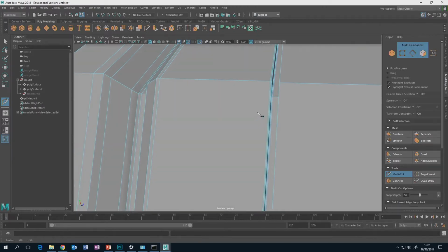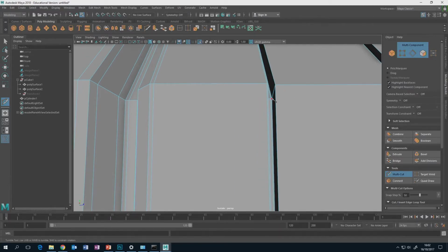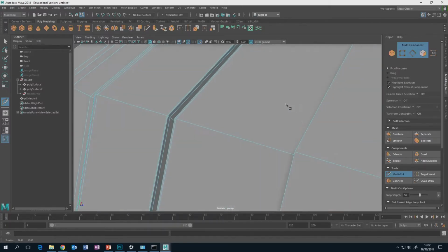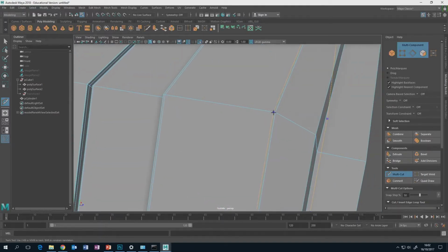Now, as I said, you could do this using the bevel command, but the bevel command will start off with a preset value in its fraction, and when you're dealing with these tiny little distances here, that fraction is going to be too big and it might explode your mesh a little bit and be initially confusing as to what it's doing. So I would say initially start off adding this stuff manually. Another one just there, here, and here. Definitely want one there, and there.